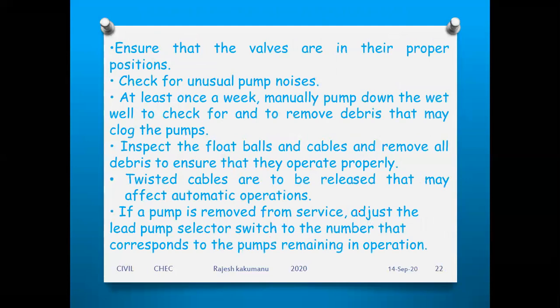Ensure that the valves are in their proper positions. So we should check the valves also. To check the valves, ensure that the valves are in their proper positions. So you have to check whether the valve is in off condition or on condition. So before starting the pumping system, you have to check whether it is off or on.